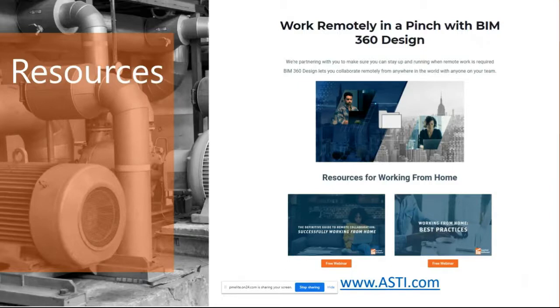But keep in mind, though, the one thing about CAD, right, model space is vast. It's up to 10 points of decimal precision. So you can literally draw the solar system to scale in model space. So if you bring in a CAD file that has like a node or a speck of sand 20 miles or 21 miles in space, when you bring that CAD file into a Revit project, it's going to blow up. It's going to cause a fatal error.